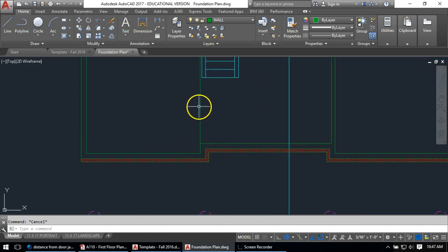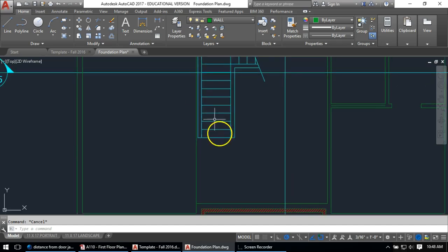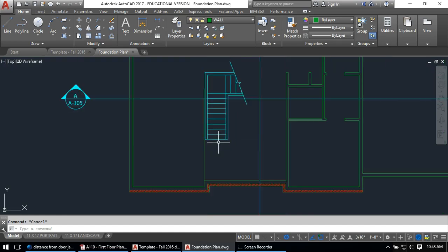The interior walls here are only 4.5 inches. The exterior ones are 6.5. It seems like there's a misalignment here at the stairs to the basement, because this is going to be a wall. This certainly can't move from the basement level to here. So I'm not sure if there was a mistake in dimensioning in the basement, or if I misplaced something in the basement. I mean, my dimensions in the basement I think worked out. But these are the things that happen when you're drawing architecture. You got to get things to be in alignment.